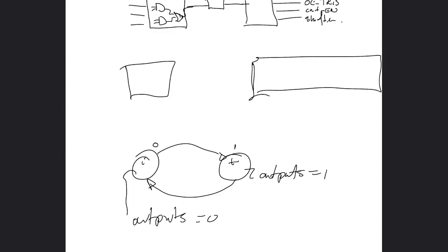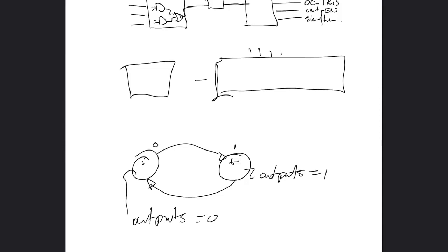Just as a quick revision, the way the shift register works is that it has a parallel input, a shift input and a shift output. It can also have a parallel output, which you will use for the receiver, but not for the transmitter. So for the transmitter, I'm just going to draw that part real quick. I said I have two states, idle and shifting or transmitting. In the idle state, I'm going to program this thing to load the values on each clock cycle, all four of them clocked in, or if it's in the transmit state, it's going to shift stuff through from flip-flop to flip-flop. So on each clock edge, and let me draw those in real quick, there's a clock input here.